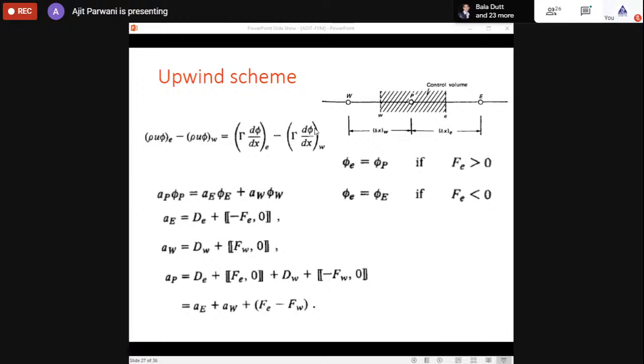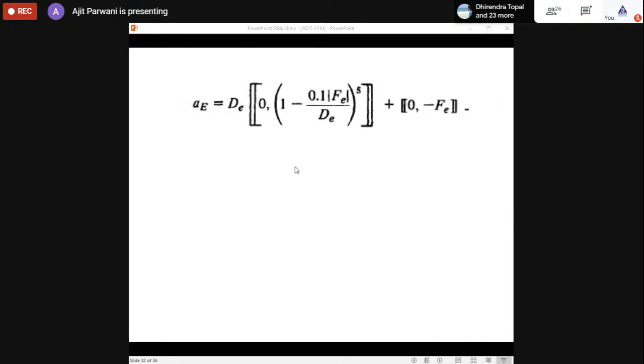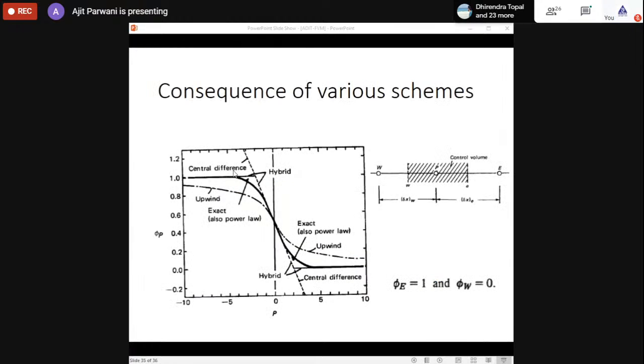So in order to evaluate this derivative term, because of this, the error occurs in this upwind scheme. This is a difference because of the wrong use of the profile function for evaluating the differential term. Okay, so therefore the upwind scheme is not real. It will give the approximate solution, but it will not give you the true solution. So what will be the true solution?